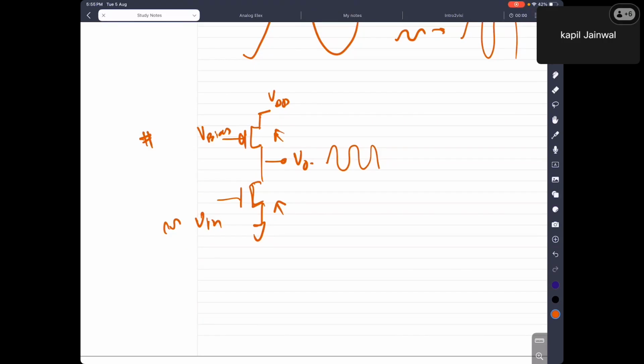Similarly, you can observe your signal with respect to frequency. That is called AC analysis. Similarly, you can observe the voltage level at the input as well as at the output. That is considered a DC analysis. Similarly, if you want to find out the noise performance of your system, then you do the noise analysis. All these analyses you do on this system.